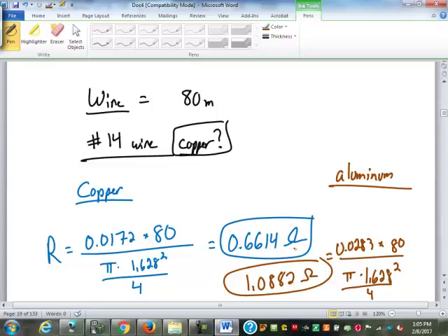So when testing that wire, if you have a reasonably accurate estimate of that length, it is not difficult to tell if that resistance is correct or not. The biggest thing that would interfere is if it goes to a hidden junction somewhere and you can't see that it's a junction. That connection loss, the insertion loss I guess is the term they use for it, when it goes through a connection, that'll screw you up.